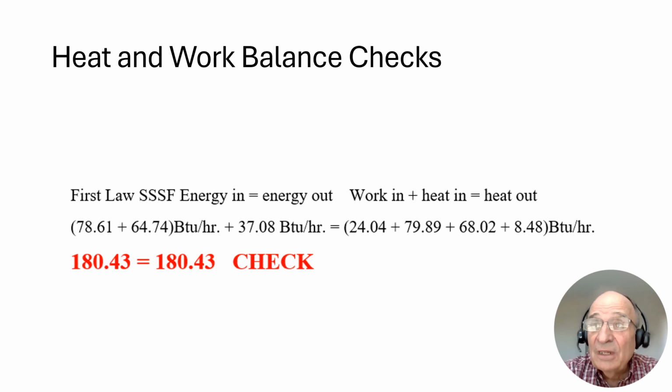If you're going to be doing peak shaving for a plant that's going to operate for a small period of time during the year, then you'd want to use a nitrogen system because your capex is low and your opex is higher. If you're going to do a lot of liquefying, let's say you're an export terminal, then you would want to use something like a C3MR, a very high efficiency process that has a very high capex but a lower opex.